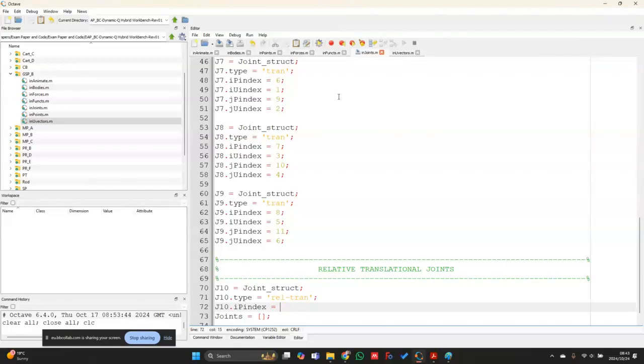Otherwise, you can actually rather do a revolute joint, I think. Oh no, that would be because a revolute joint acts between two revolute joints that you have. So you have one on the ground, but if you remove the bodies, then you don't consider that revolute joint. Yes, so you would use a revolute translational joint.